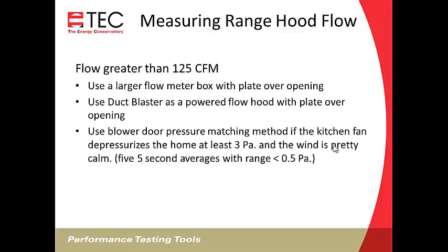Or use the blower door pressure matching method, again, that we talked about. That works if the kitchen fan depressurized the house at least 3 pascals, so you have to have either a fairly tight house or a fairly big kitchen fan in order to get that amount of depressurization, and the wind needs to be pretty calm.